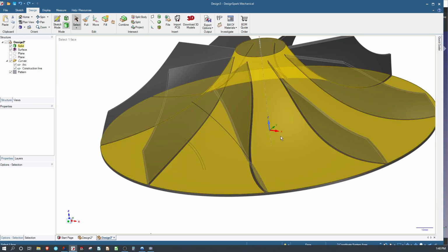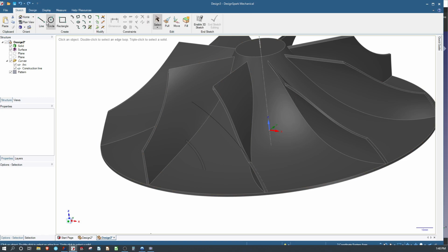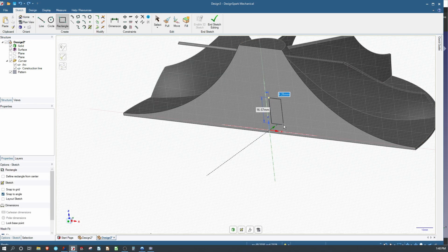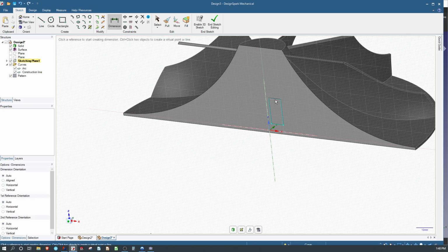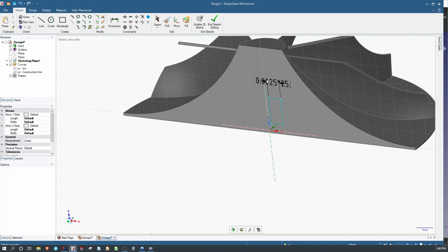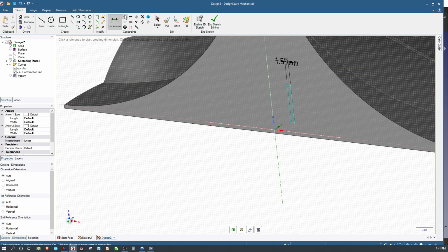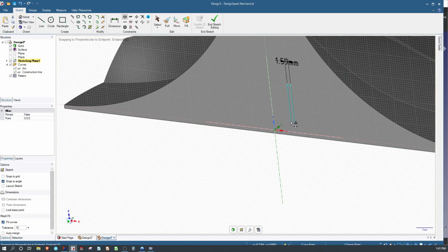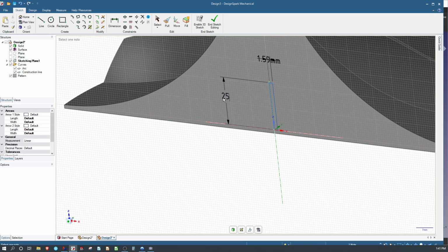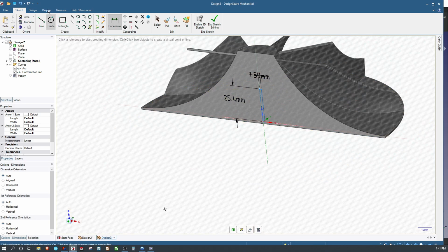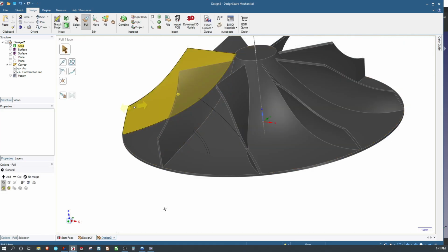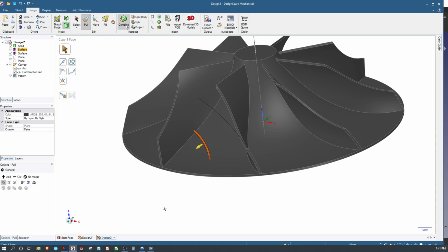And let's utilize a different tool that's still pretty simple. I'm going to highlight my ZX. We'll hit Sketch and make a rectangle, and now we're sketching, of course, on our ZX plane. We'll go with a dimension of 0.0625 times 25.4, consistent thickness. We're going to go from here to here. We'll grab our dimension here and say 25.4 in height, and I think we're fully constrained. So we're going to hold Control and select this and choose Blend.